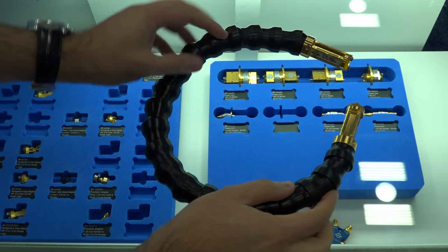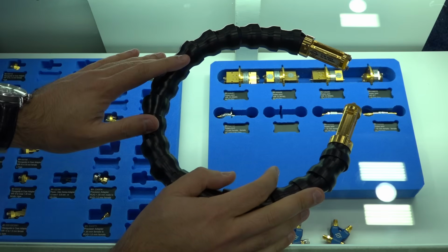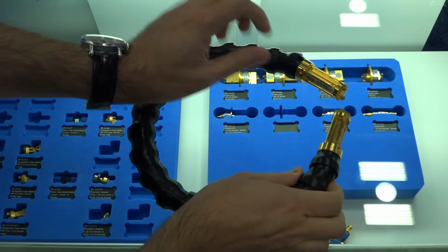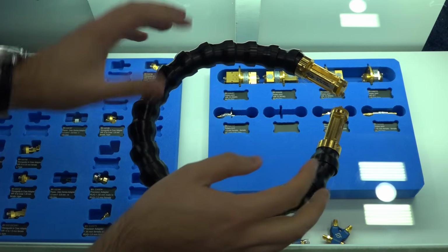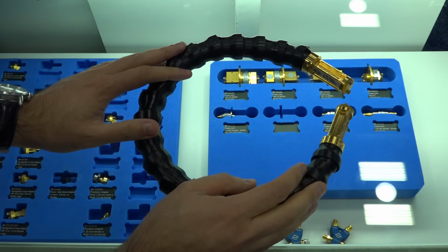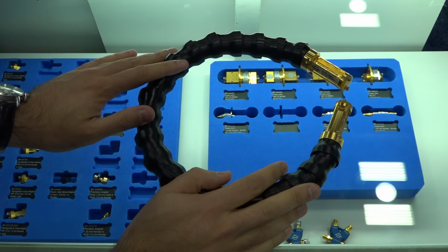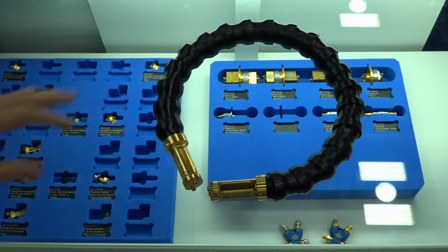So something like this, I think 600 millimeters or so, between 3 to 4 dB of loss at D-band, 110 to 170 gigahertz, is really impressive, especially how flexible it is overall, with of course rigid waveguide connectors at the end. So this means you can now connect really unusual pieces together in an S-parameter setup, leave it, and then it will stay stable with really good loss, not eating into your dynamic range. Definitely one of the best performance flexible waveguides I have seen.